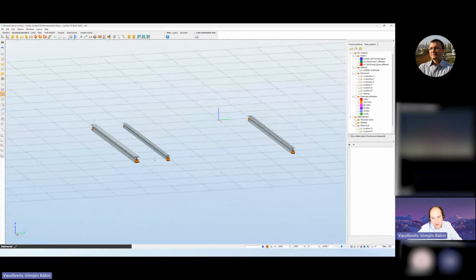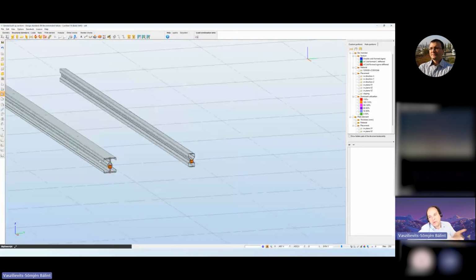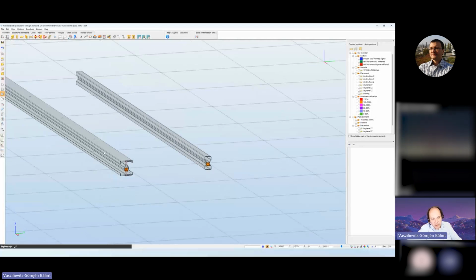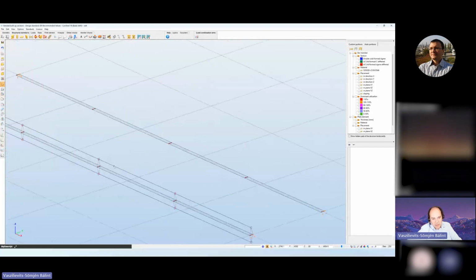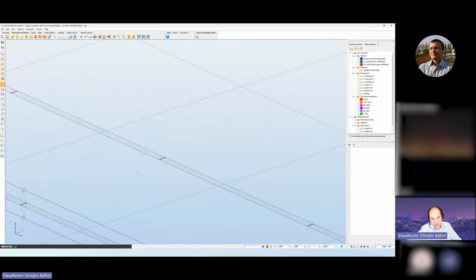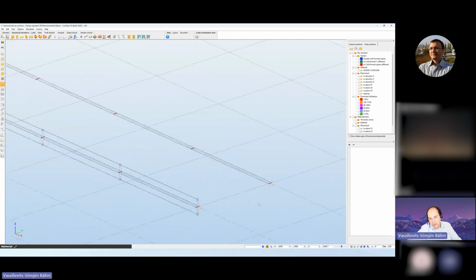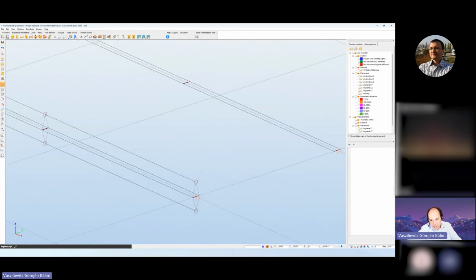This is now a Consteel model where you can see on the left side two such old style built-up profiles. They can be very complex, made of several profiles, but if you look to the structural view, now you see that there are individual reference lines, and as I said, these individual reference lines are connected with link elements. And of course, when we are at the end of the member, then somehow we need to make sure to connect the four individual lines to the connecting elements, or try to somehow merge them together into one node which has a beam-like deformation, and then connect this only point to the connecting member. It's always possible, but it's a bit difficult.